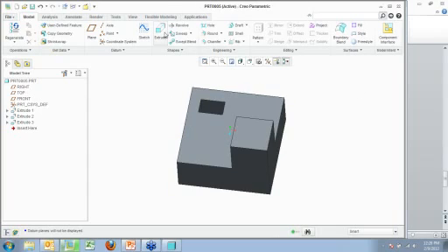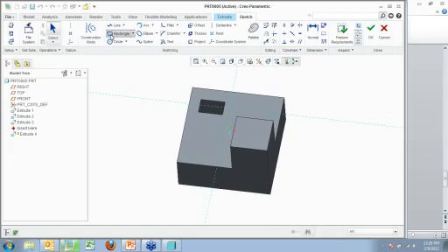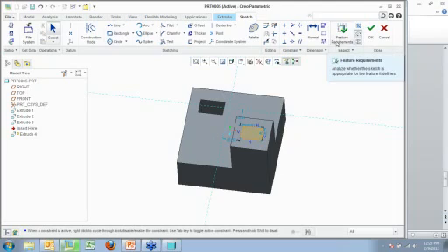So let's hop back in. We'll do another extrude right here on top of this, just to show you some Sketcher stuff here. So you noticed when I completed something, and this isn't a new feature by any means, it's shaded by default. That is on by default in Creo Parametric. That was an option in Wildfire 5 and maybe, I believe, Wildfire 4 before that. You have your feature requirements: shade closed loops, highlight open ends, and overlapping geometry, which, these two, shade closed loops and highlight open ends, are turned on by default now.